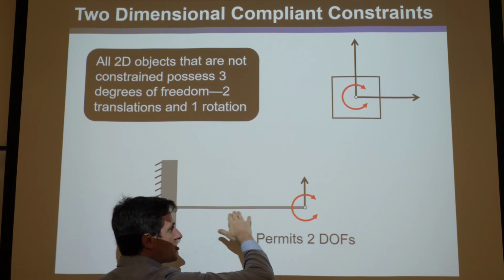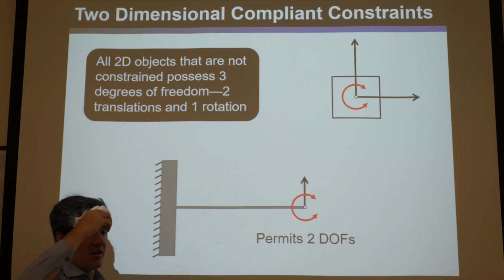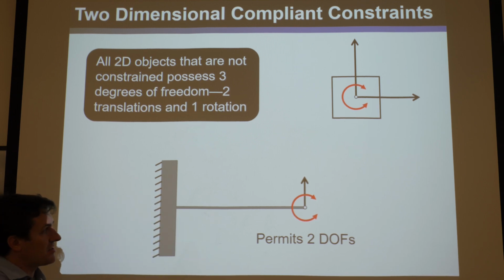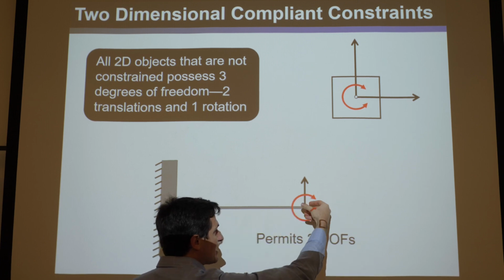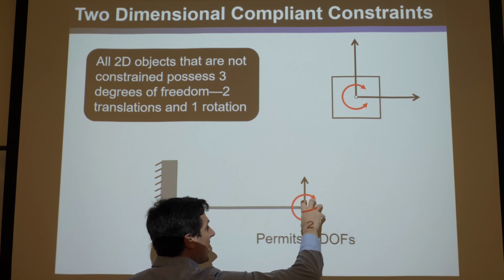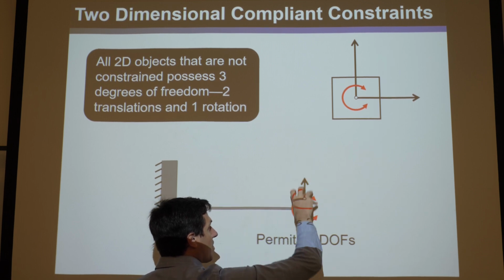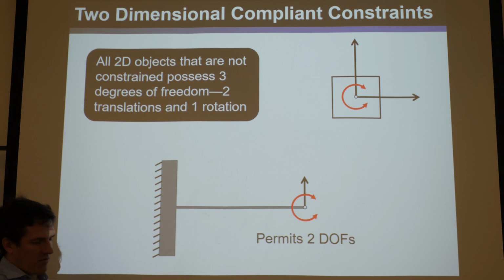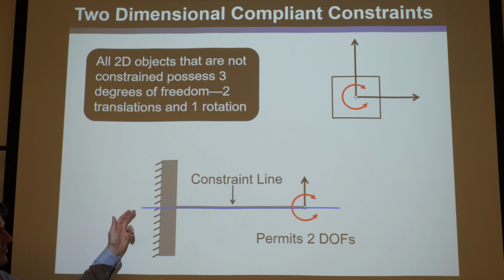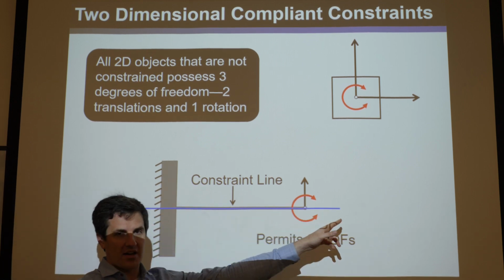And by the way, you want to assume it doesn't really buckle. We're going to make some ideal constraint assumptions. But anyway, it's better to visualize. It's much stiffer in tension than it is in the orthogonal direction and in bending, right? So you would model this in constraint-based design as an ideal constraint. You show them as blue lines that go through their axis.